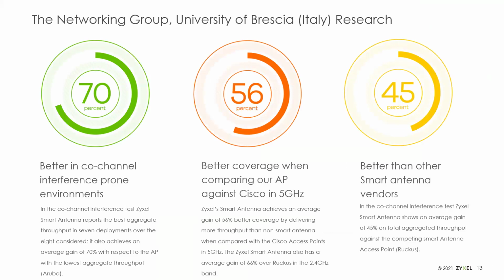And again, we talk about this in the Wi-Fi 101 webinar, but basically, ignoring MIMO technologies, generally each device has to take turns broadcasting. You cannot have multiple devices broadcasting at the same time using the same channel. So anytime you have multiple APs in an area, due to the limited bandwidth, you tend to get co-channel interference because some of those APs have to use the same channels as some of the other APs. There are also other additional sources of RF interference, particularly in commercial and industrial areas, that can cause this interference. So smart antenna outperformed regular antennas.